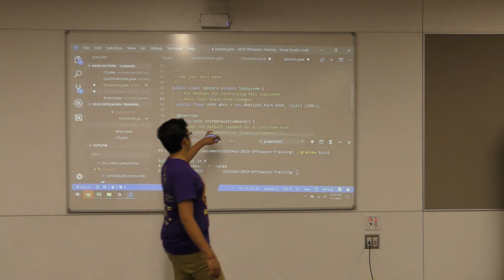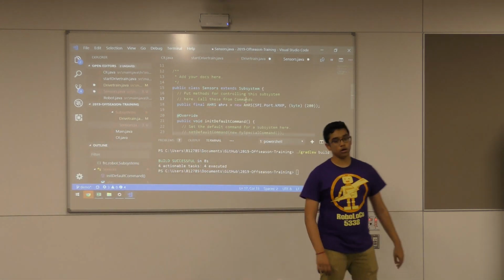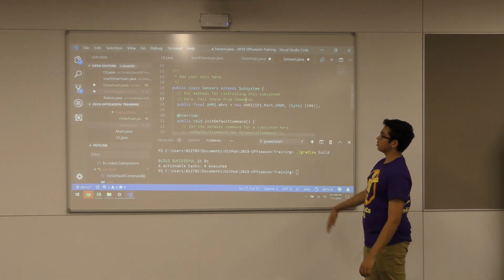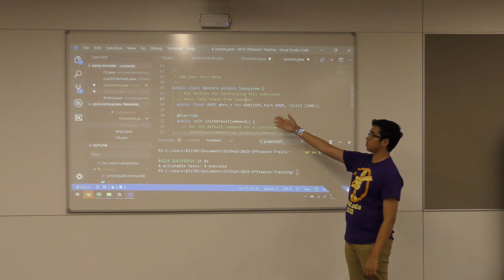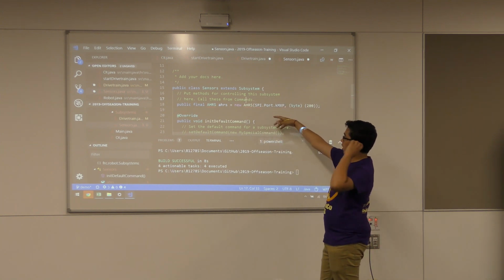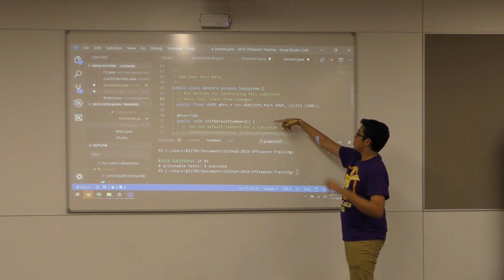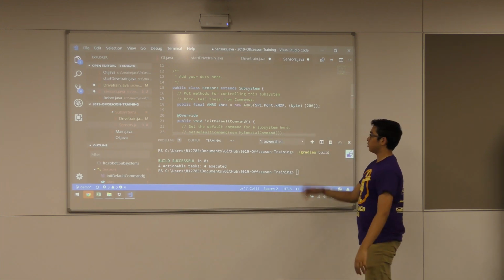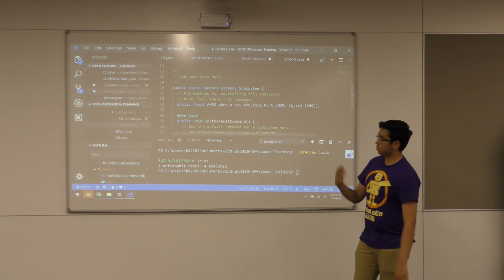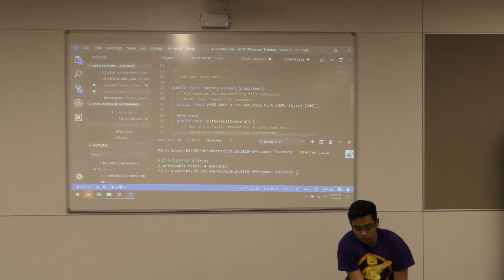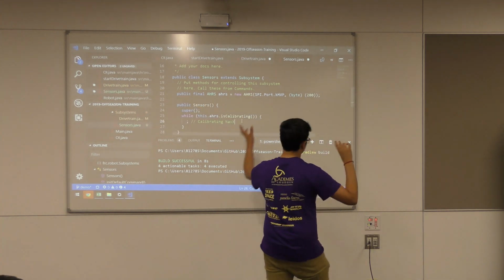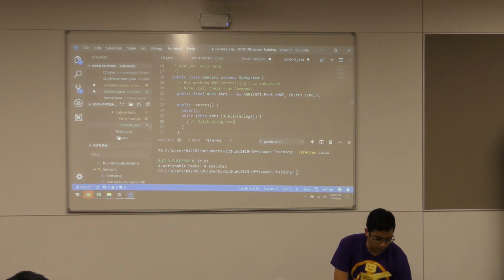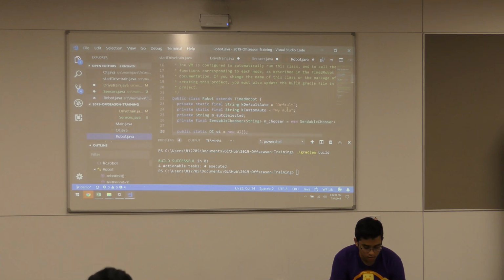Whoever created sensors, the way we define our gyro sensor is an AHRS. So public final AHRS equals new AHRS, and these are just information about the NavX that we have to pass in. Not too important where we got that. The AHRS is pretty simple to use. Since we created our sensor subsystem, we have to go into Robot and actually define it.